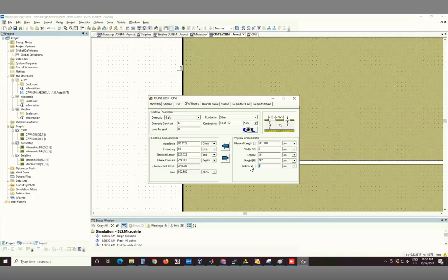Now, if my gap is only 10 microns and my height of the metal film is 35 microns, you see that the thickness now starts to play a big role in the overall structure, whereas these simulations are actually meant for more planar type of circuits. So we never make 10 micron gaps in this particular circuit board. I was thinking of the other kinds of chip we make, where usually the thickness of the film is only 100 nanometers.